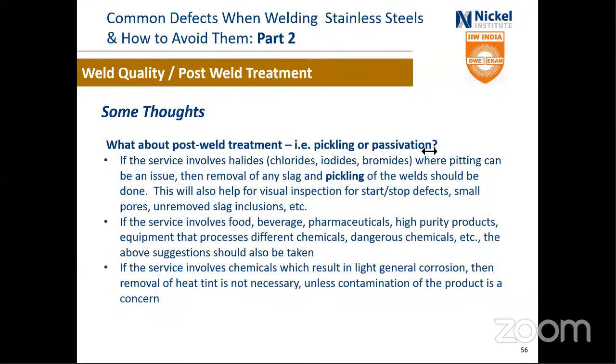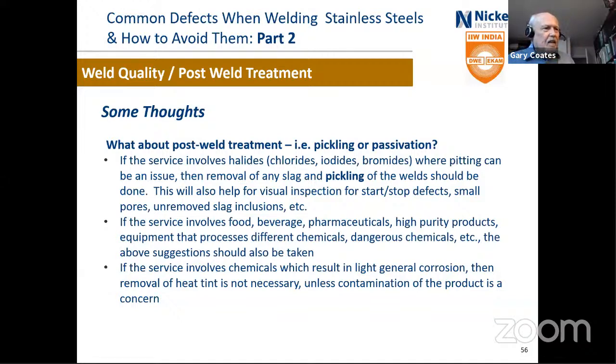Should the repair welding procedure of aged or used material be the same as the original? Will there be a change in filler metal? What other precautions need to be taken? So this is regarding a repair weld where the material is already aged. Yeah, certainly you don't need to do anything different if you already have the procedure in place, but you do have to ensure things like cleanliness, that the material is not contaminated in any way.